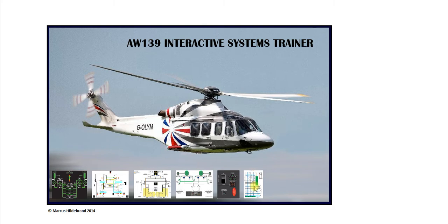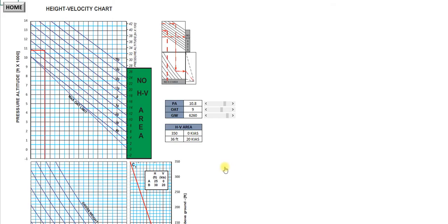In helicopters it's very performance chart intensive and all of them are incorporated into the respective RFM of the aircraft, and you generally have to look up these charts, enter them with a ruler and a pencil and come out with some numbers. And I find it a lot easier just to put the charts into Excel,